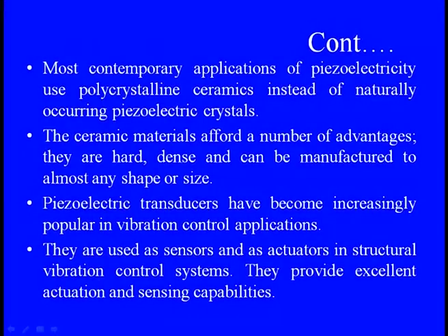Because of the inherent property of stiffness, which is the force per unit deformation, and the variations in stiffness, these materials generate large forces when their natural expansion is constrained, giving the actuation feature. At the same time, they can sense molecular motions through the change in electrode and strain features. So the piezoelectric material can act as a sensor and also as an actuator.